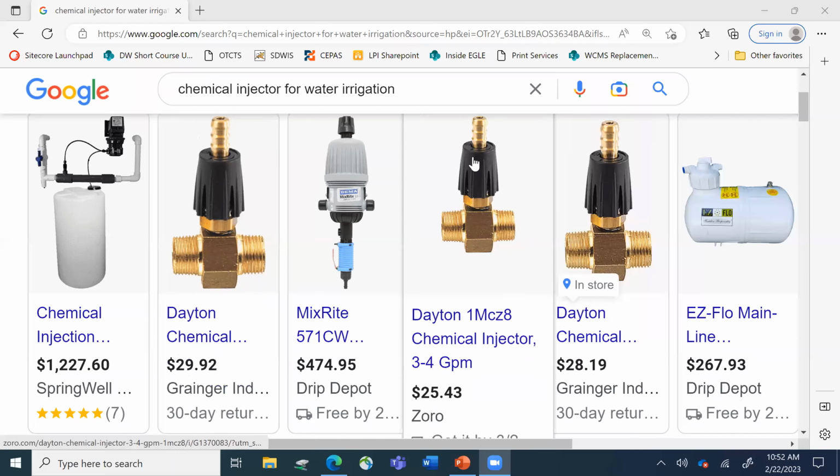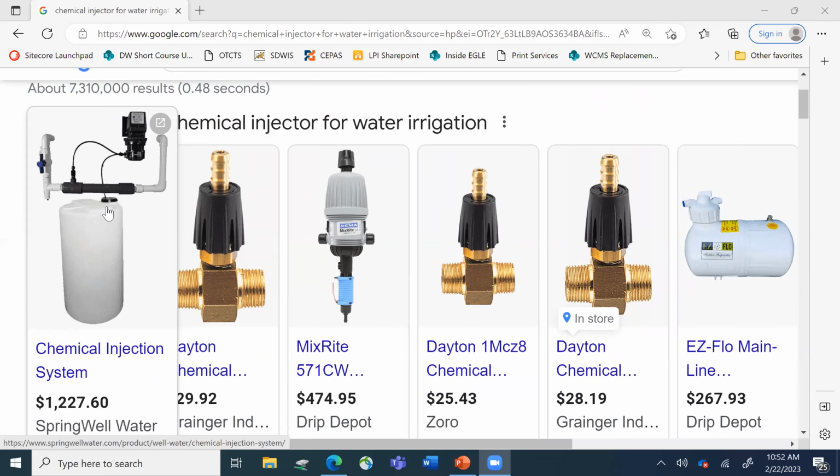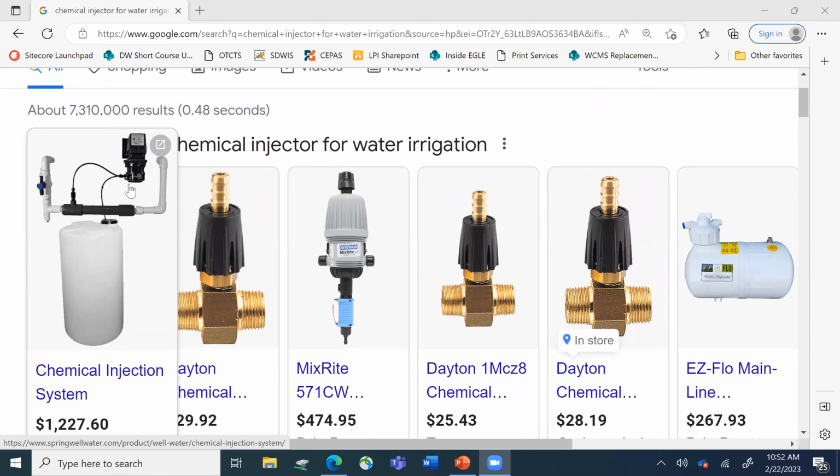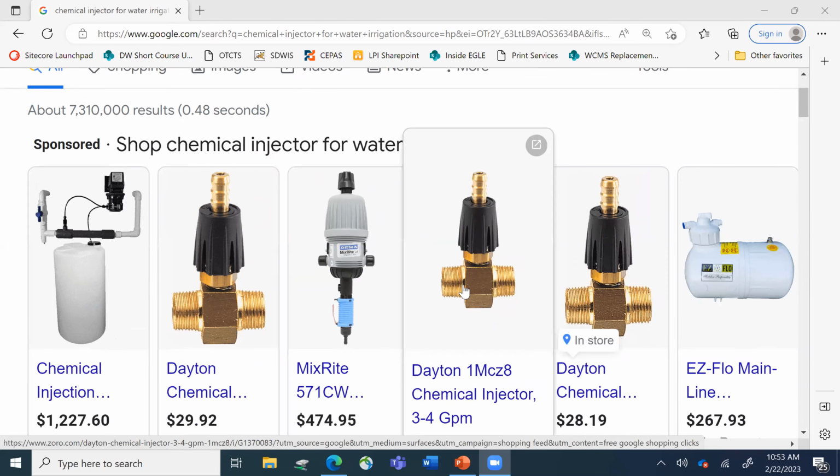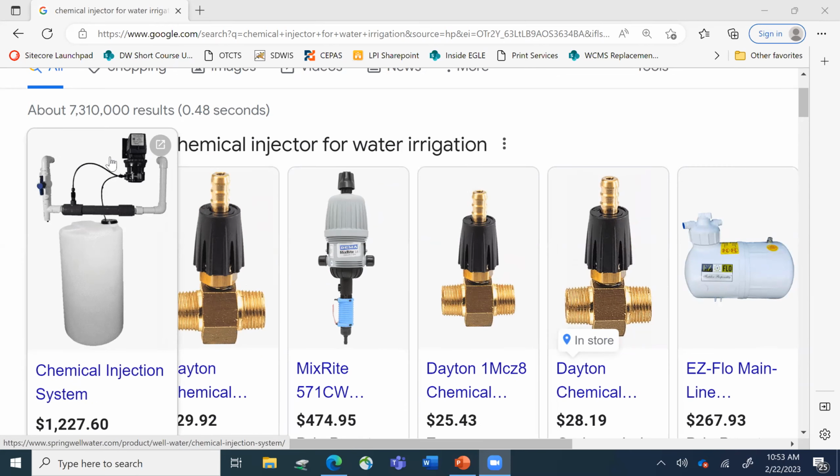Share screen. Okay, hold on. They look like this. So you'll see a little inlet like this that has a flared nozzle on it for a chemical feed, and then it'll be hooked into another device. The device can be a different kind of pump, called peristaltic pumps and diaphragm pumps. But typically the thing you're going to look for is a copper connection with a spline out of it and a little hose. Does that make sense? And you see how it's spliced into a water pipe here? That's the main two ways you can see it.